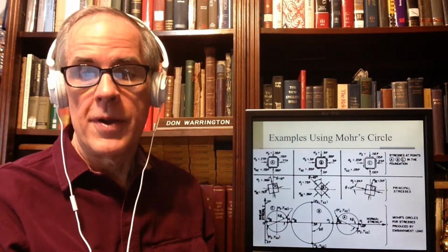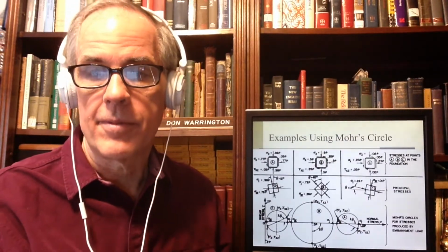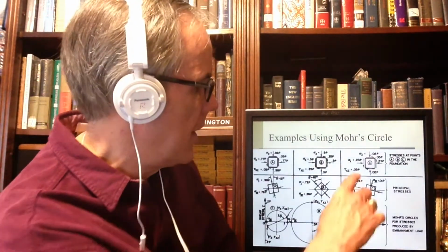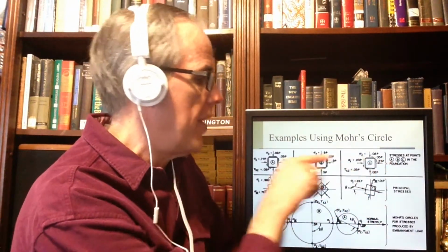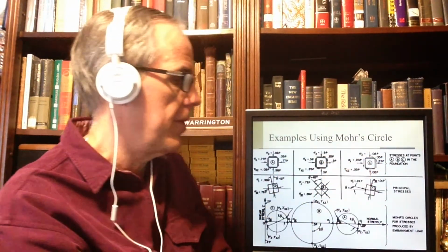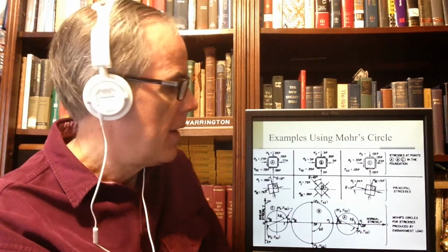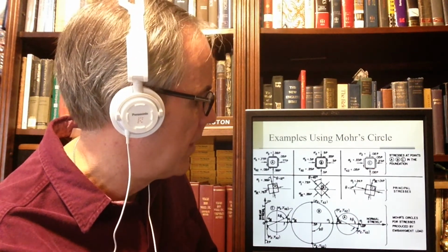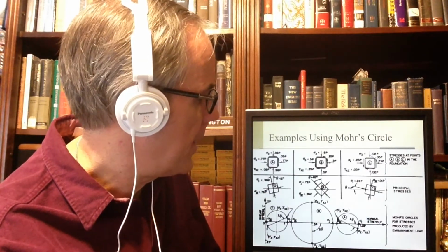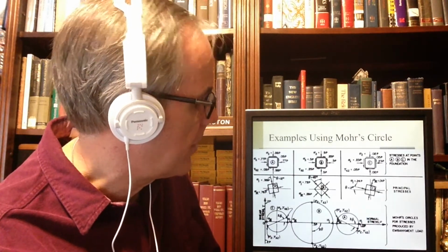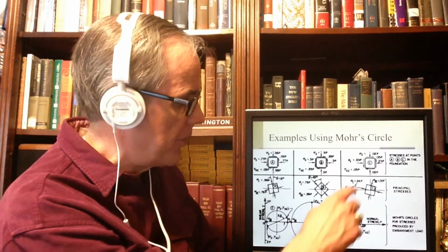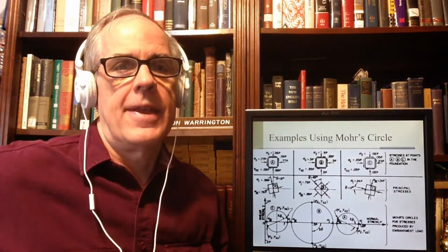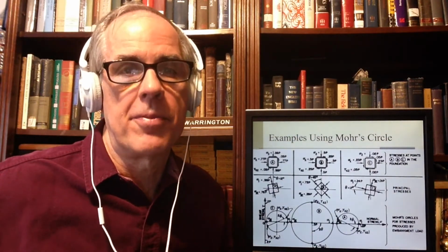The last one is loaded very lightly. Over here, the horizontal normal stresses are actually greater than the vertical normal stresses. The shear stresses are substantial enough, but not really, because if you plot these on Mohr circles, this stress state goes here and here. And by the way, it doesn't make any difference which one you plot first.